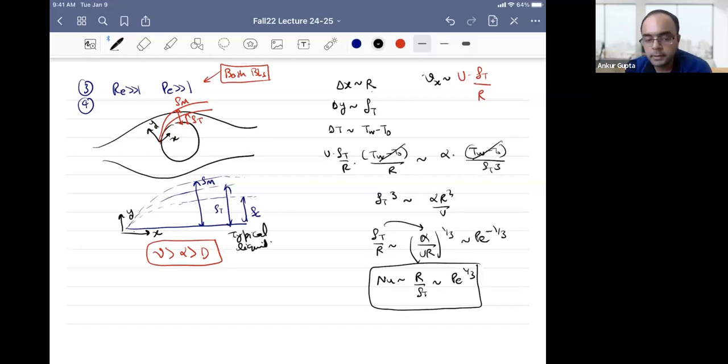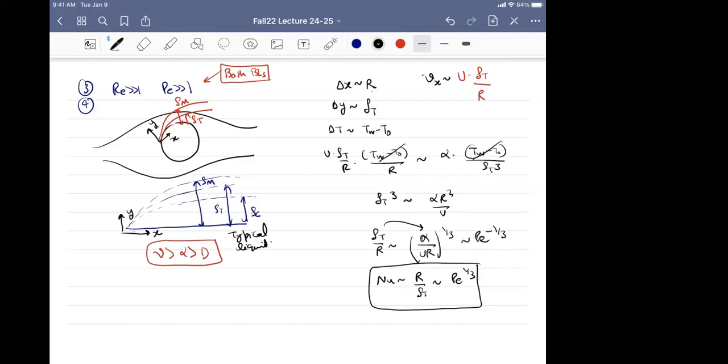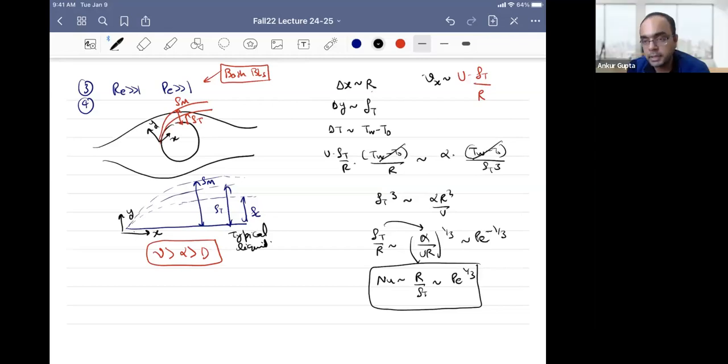Is the length of the boundary layers related to how fast the profile develops or not? Yes, absolutely. The thickness of the boundary layer does depend on velocity always. But relatively, the three of them will always have this. But yes, the thickness of all of them will change. If you have a velocity changing, then the thicknesses will change. Like we see here, right? Whenever you have the velocity to be large, the thickness decreases. That will happen for all of them.